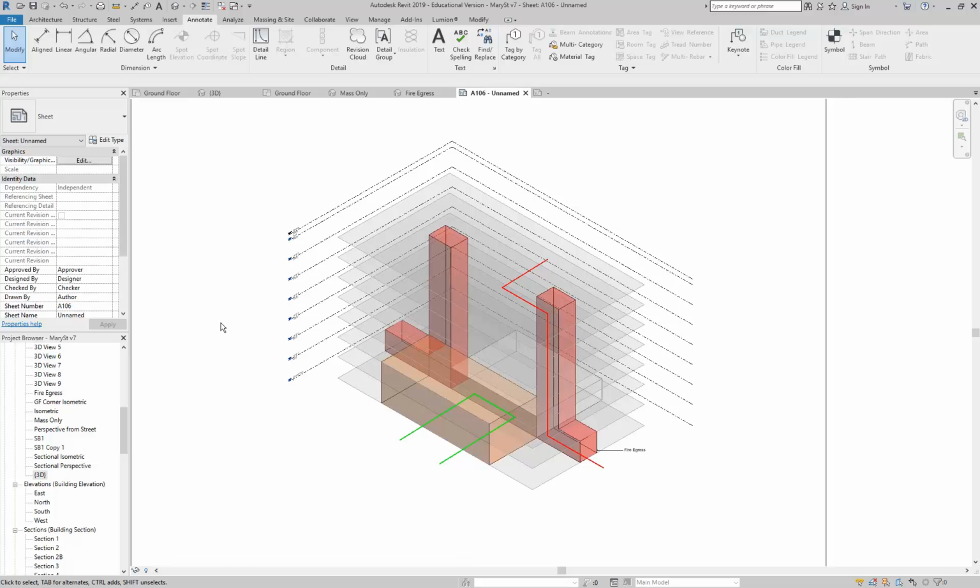And that's really important, so I'll give you a tip. Anyone doing the tram sheds, you've got those sawtooth roofs. So you can show in a diagrammatic way how you've got to get both ample light and some sort of view out, because that's a big problem. I've actually worked on buildings just like that, where you've got to get the height of the bedrooms just right so that they don't just have light coming from the windows above, they can actually see out of those windows a little bit.